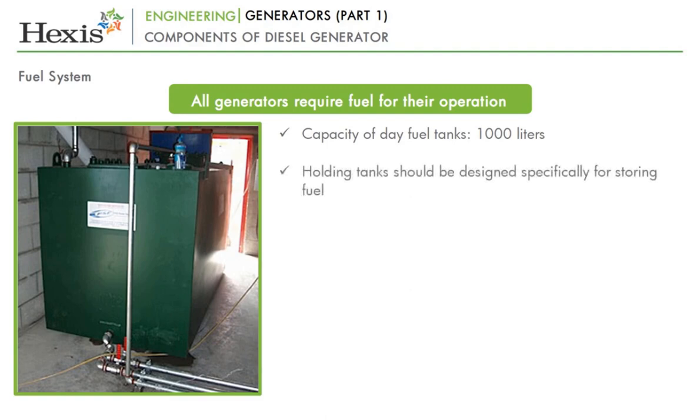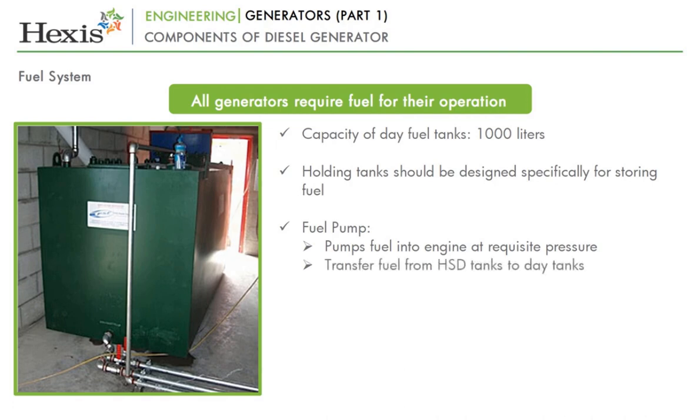Please note that fuel should be stored in holding tanks designed specifically for storing it or in an approved storage container. Fuel pumps are used to pump the fuel into the engine at the requisite pressure through fuel lines to each cylinder of the engine. In order to transfer fuel from HSD tanks to day tanks, fuel pumps are used. This pump contains filters or strainers that ensure only clean fuel goes into the engine.